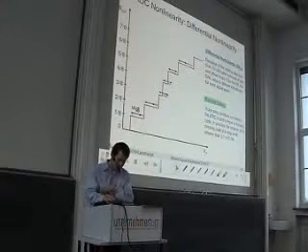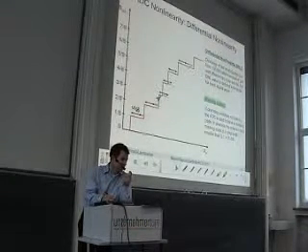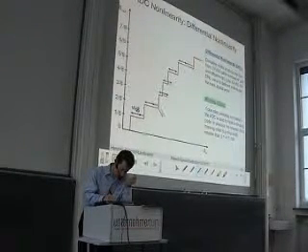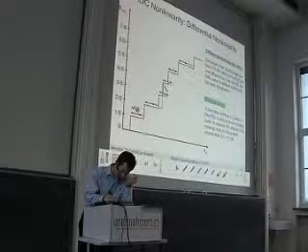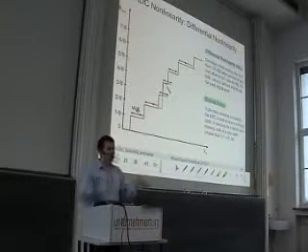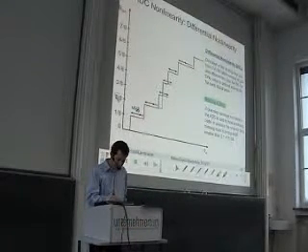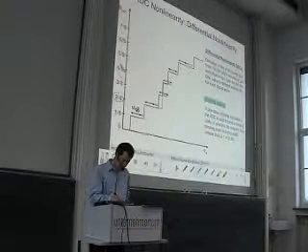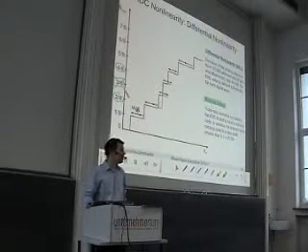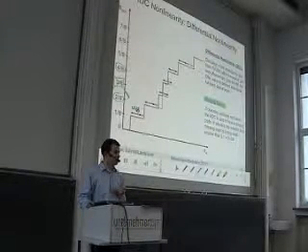completely. For instance, if we look at this step here, which is already quite small, if this step width is reduced even further, then at one point the step vanishes completely, and then we would have something like this. Then this code never occurs. Okay? If you have all possible input voltages, then you get this value, this value, this value, but you never get this one. This one does not occur. And this is what we call a missing code, because this code is never visible at the output.